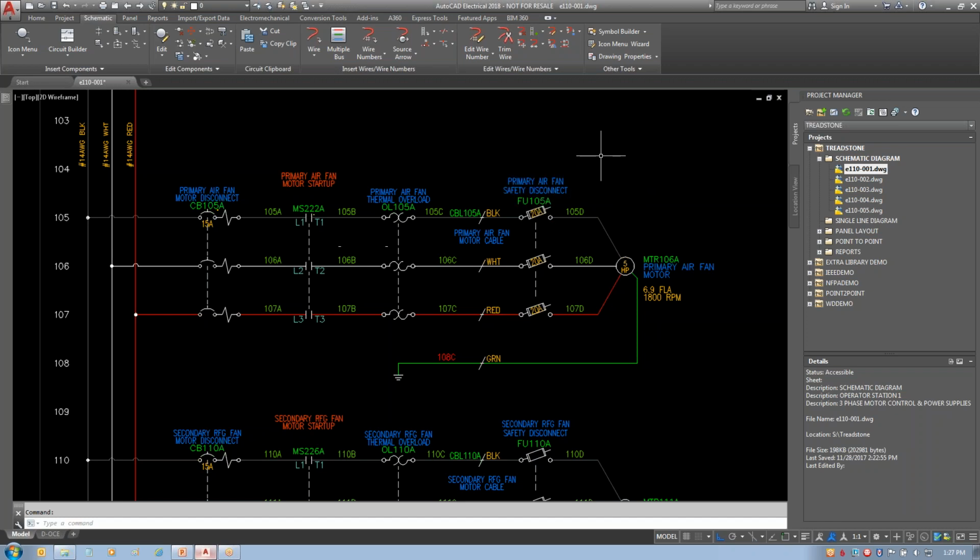Also, in addition, you'll notice here that I am using a fuse switch for the three-phase on the motor. I chose to do that instead of a fuse simply in order to show what was necessary in creating a custom symbol for a single line, one-line component, because they are different than just a normal schematic symbol, but very minor how they're different, but I needed to show that. And there's not a fuse switch out of the box here, so that's the reason I chose to use a custom component here for that.